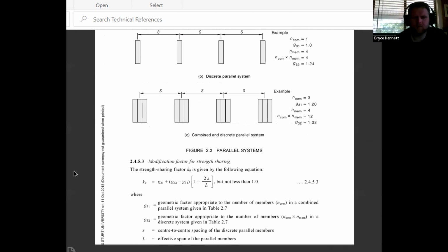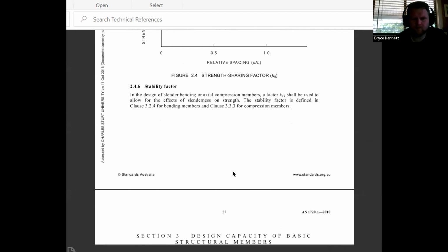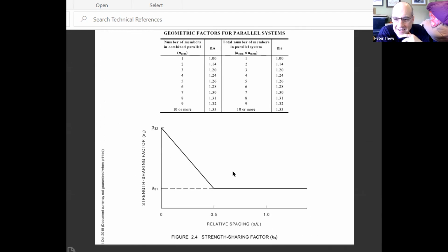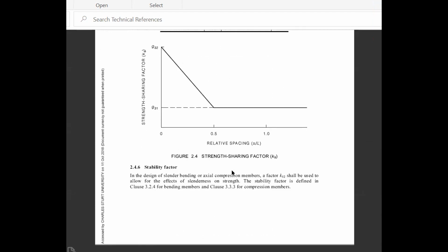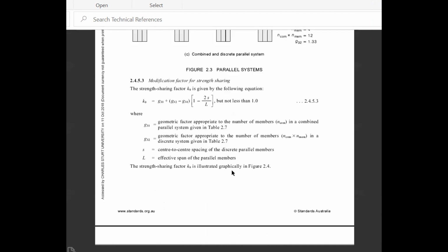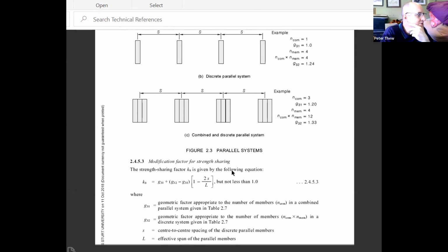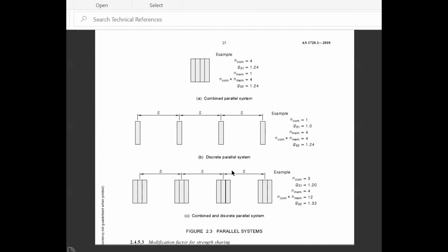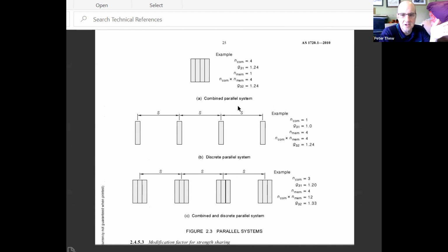Yep. All right. K12's a pain in the rear as well. Sorry, I was muted. So it said somewhere that glulam and laminated timbers are always one. Is that right? Yes. Can you tell me why that is, or do you want me to tell you why that is? Was it something about that they're much less likely to have localized defects? Glulam and LVLs are already made up of a bunch of different laminates stuck together.